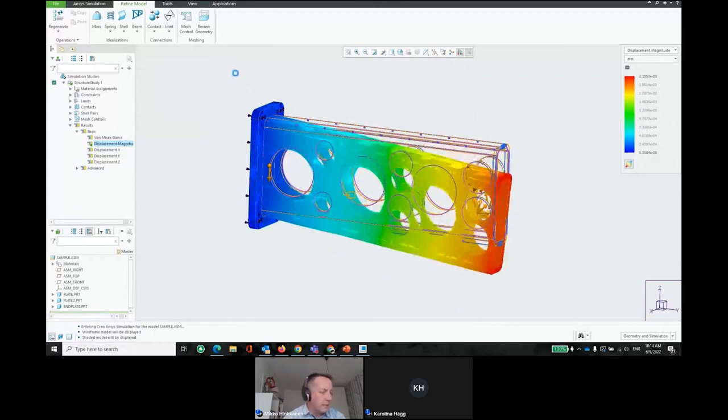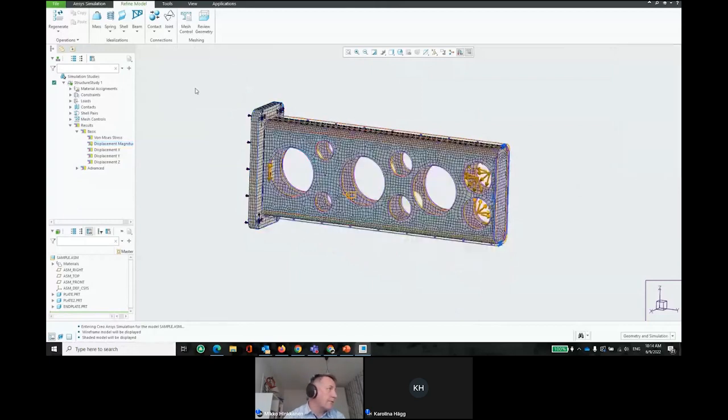Was there anything else? Shell creation itself. Well, if you want to do shells, you can do them from surfaces. Just click the surface, as you do with surface modeling, and define the material property and the thickness of the shell. On the other hand, for shell pair, you manually point out that these are the matching pair, which is then compressed to mid surface. Or you can give a number, and the system will automatically find all the matching geometry that might be there.